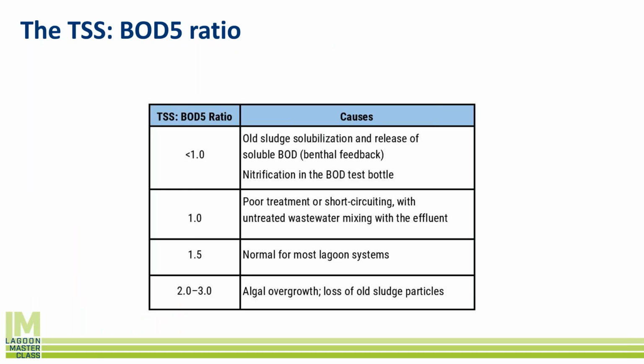First of all, because really what most of our permits say nowadays is CBOD, and this is sort of an interesting thing because I'm lazy too, and even though I know it's CBOD on most of the permits that I work on, I still say BOD because it's just kind of cumbersome to say CBOD. So that is one of the things we can look at from a testing perspective: are we doing the right test? Do we need to add a nitrification inhibitor?